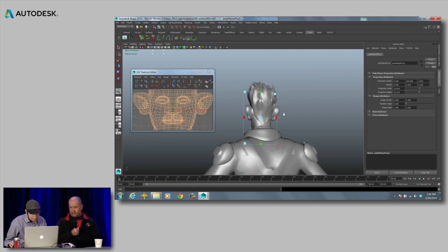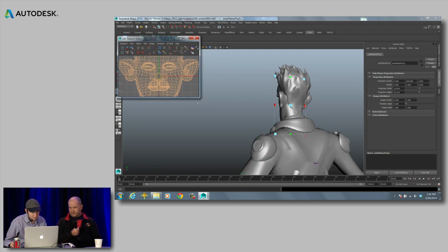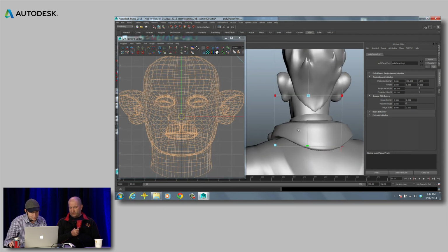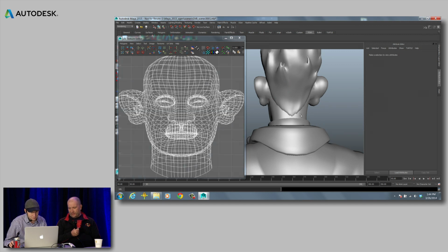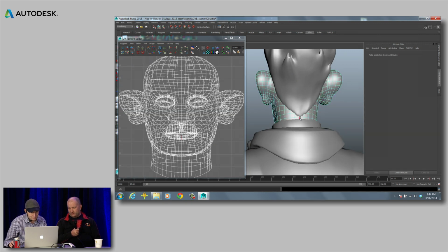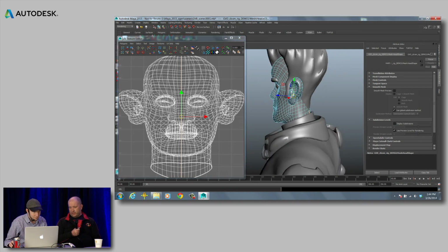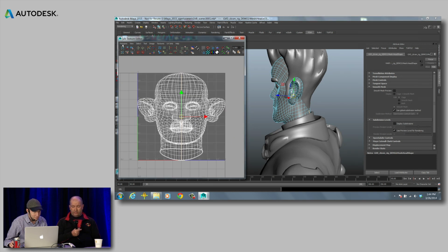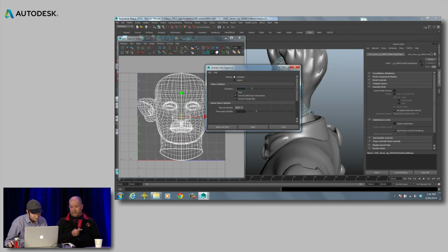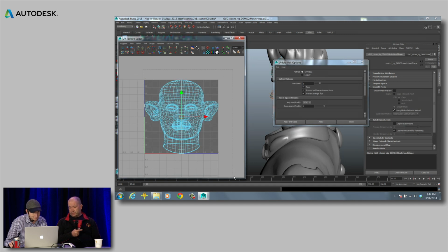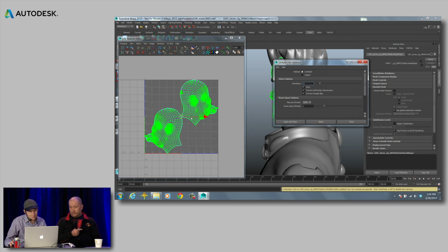I mean, this is Daryl's right now. He's just doing a default projection on Sven's head, and you can see there's lots of overlaps and lots of degeneracy in there, and it's not going to be a very good projection. That's not something you'd want in a UV layout. But with the Unfold 3D algorithm, you can optimize that and get a really nice layout really quickly, with very minimal effort after the fact to clean it up. That's one of the reasons why I put this Unfold 3D algorithm in there, because it's just way better. And there you go.